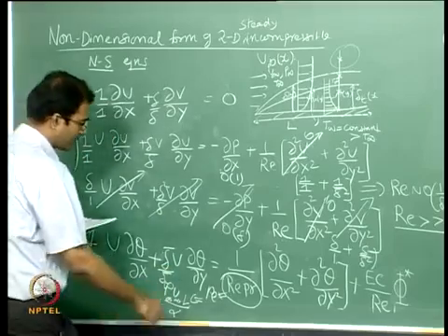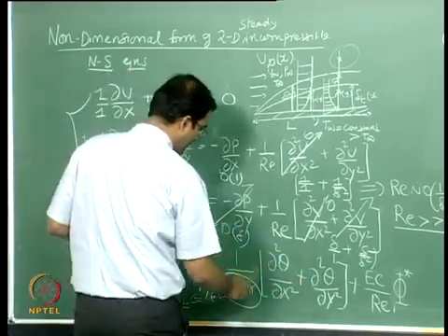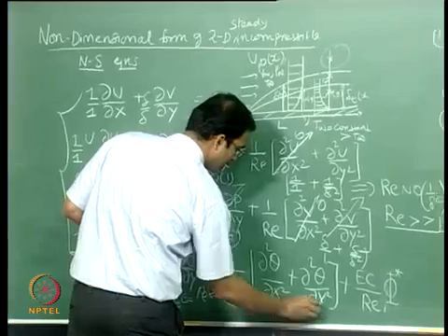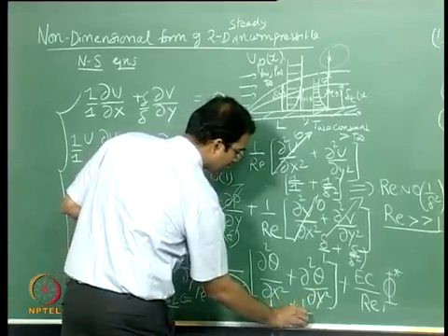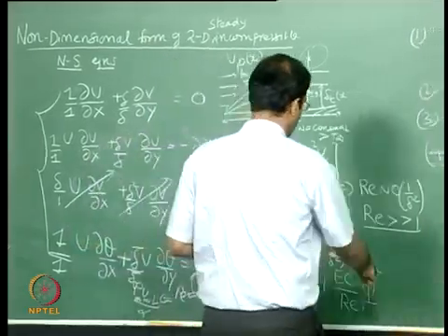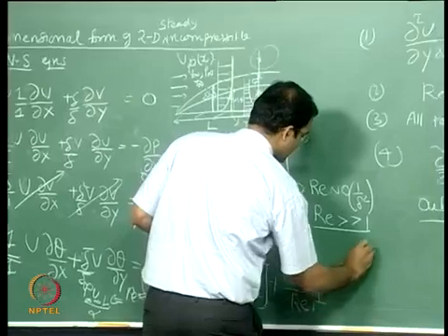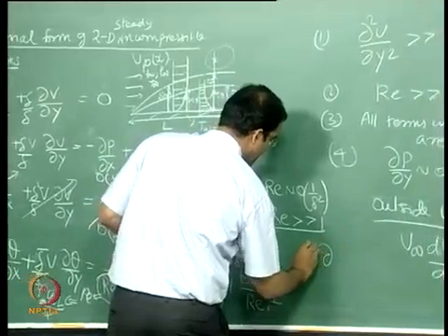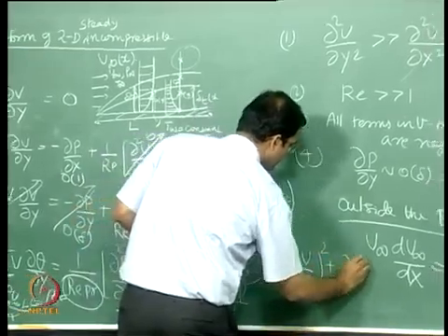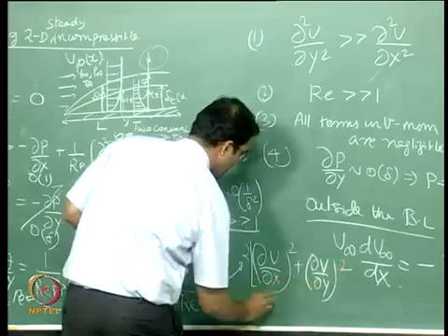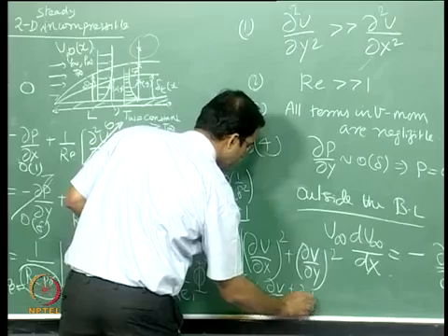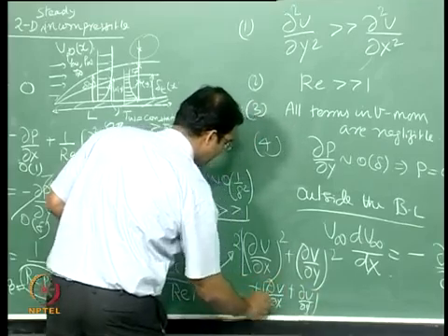Alright, so coming to this term right here, this is of the order of 1 plus 1 by Delta T square. I do not have space, I am just squeezing in. And coming to this term right here, the order of magnitude of phi star, I can write this as 2 times du by dx the whole square plus dv by dy the whole square plus dv by dx plus du by dy, multiplied by half, the whole square.